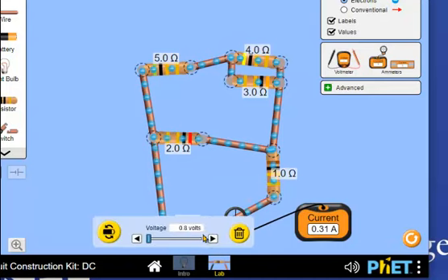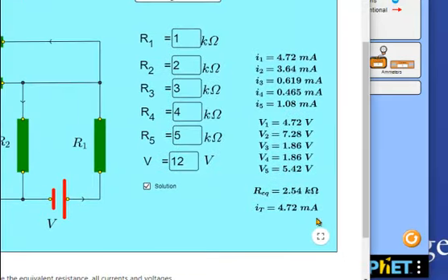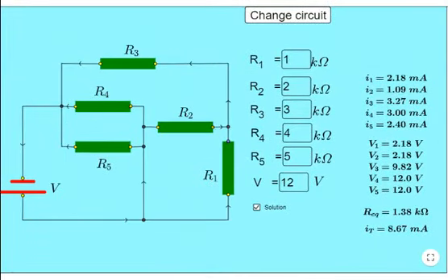Okay, so I have to turn the battery voltage up in order to get my 1. Again, that's only for convenience using Ohm's law. So either there or there, so 2.5 or 2.6 divided by 1. Make it 2.55 divided by 1 amp, excuse me, is 2.55 ohms. And when we look at this one here, true enough, 2.54 ohms. All right, and he has a 5th one apparently. There it is. And that one took me just the longest time.